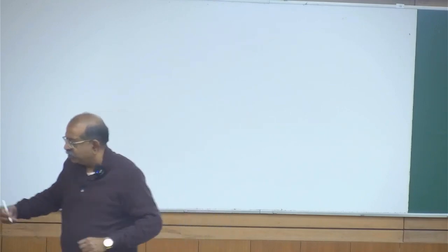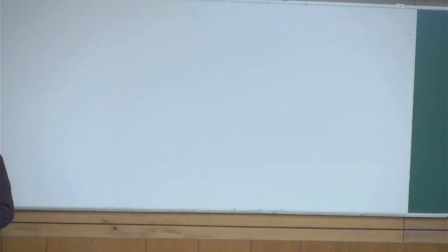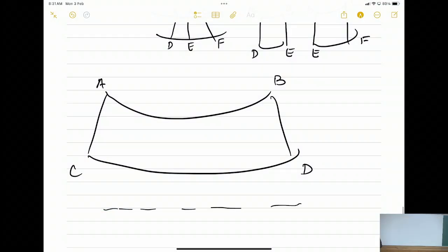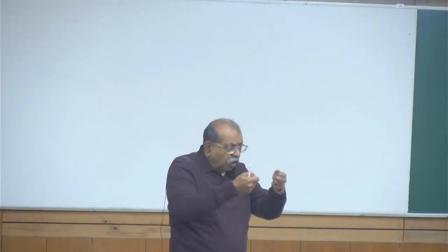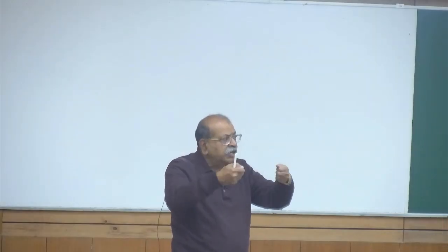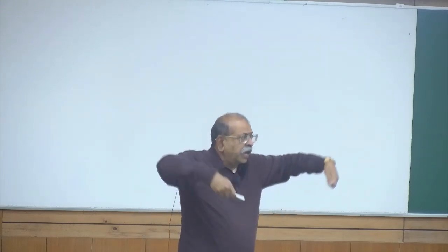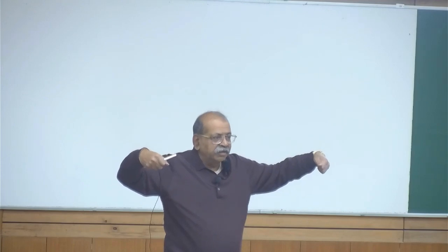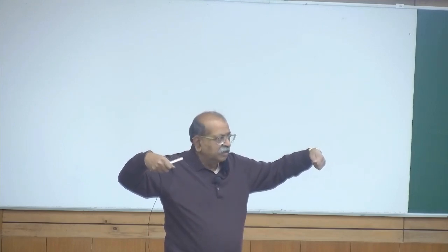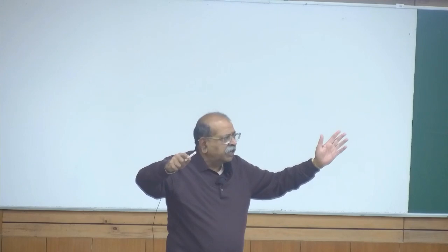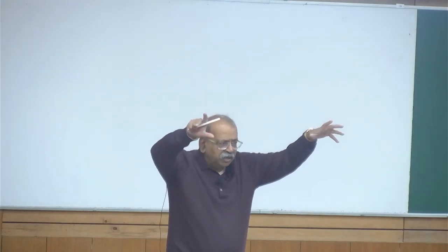See, initially everything was a straight line. Now the same material has got curved. So what is going to happen is, portions in the top half or somewhere in the top, they are getting contracted. The strain there is negative, whereas on the bottom side, they are getting elongated. Because earlier everything was a straight line, now it turns into a circle.